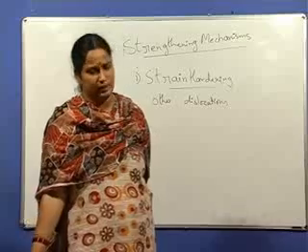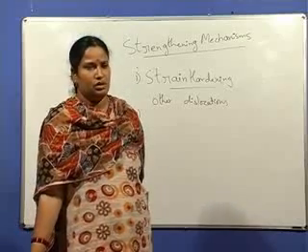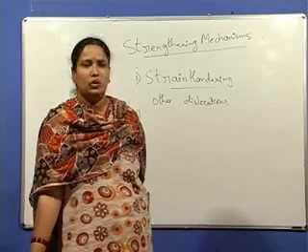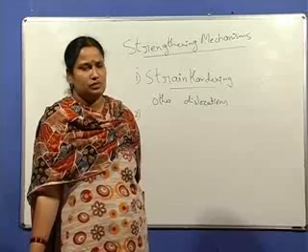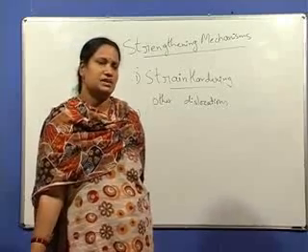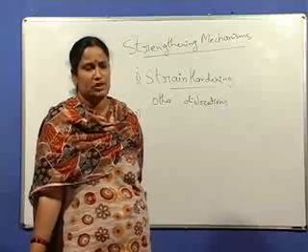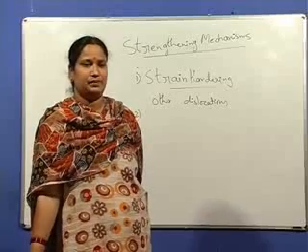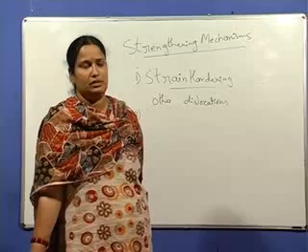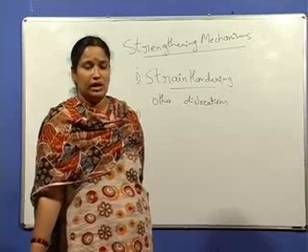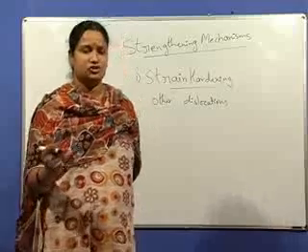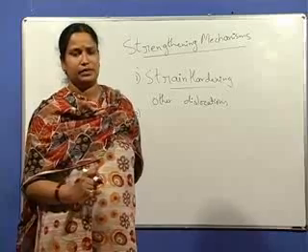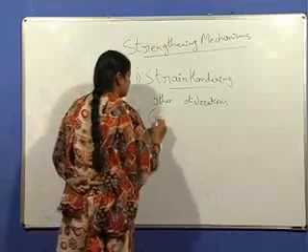Boundaries can be high angle grain boundaries, low angle grain boundaries, or sub boundaries, and all of these act as obstacles. But among these, grain boundaries are not penetrable by moving dislocations. They offer more resistance, more restraints, for the moving dislocations. So grain boundaries.